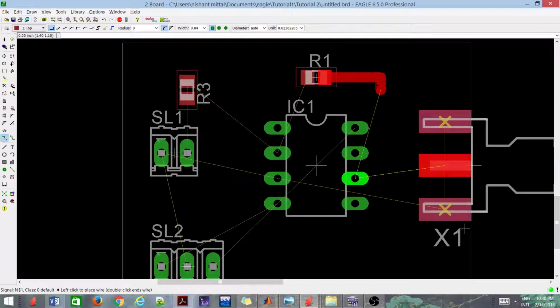Okay, now see, there are two ways of routing. One is you can go directly 90°, but going directly 90° creates current-related problems in this corner, because it may cause some current flow problems and some losses, causing some inductance, capacitance effects and all those things. So it is always recommended to have some angle, about 120 degrees, in order to have a good current flow.